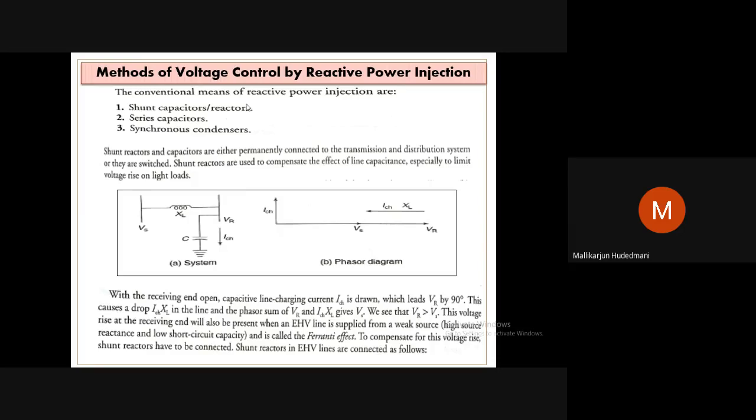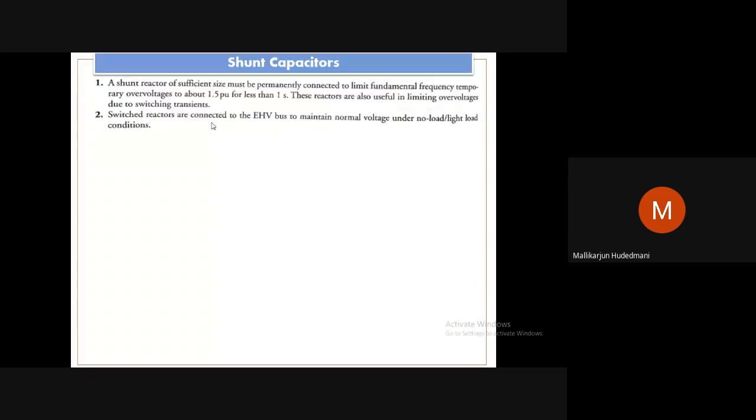So this is not going to compensate the particular total reactance. As and when there is a load, compensation is taken immediately that way. This is one simplest method, hooking it in parallel according to the computed leading volt ampere as per the requirement. That has to be balanced by your suitable switching mechanism and control. Still better than this, if you could see, is the series capacitor approach. So I have this next phenomenon.